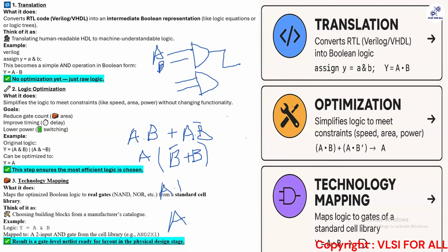Now, for example, this is VDD. If your VDD is reducing, the delay of the cell will increase. If you look at the graph, let's say this is your voltage and this is your delay, which I'm giving as tau, the industry standard. As your voltage increases, your delay will decrease. But now, I stated your voltage has moved from 0.67 to 0.6 because of IR drop. So your cell delay has increased.